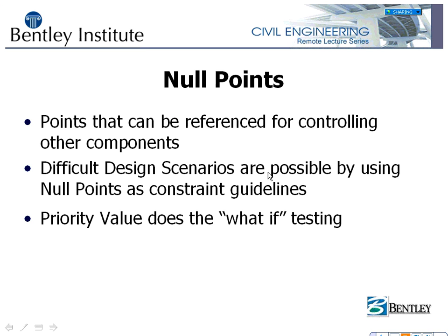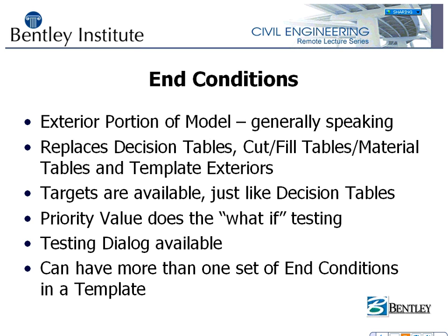The end conditions, I'm going to let it come up for a moment here, are the exterior portions of a model, generally speaking. That's not really true anymore, but generally speaking it is. This replaces the decision tables, the cut fill tables, material tables, and the exterior template intercept techniques. So when you hear of an end condition, that's what that is. Really, that means you're replacing your decision table or whatever. And if you take and import a template library with decision tables, it will bring it in, make components of each decision table, and make it where you can use it in the new modeler.